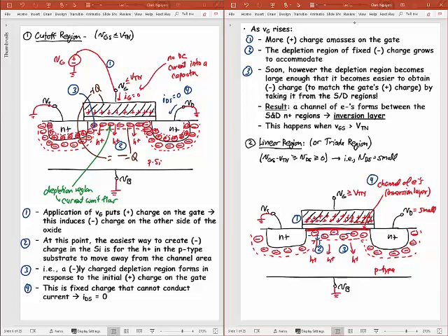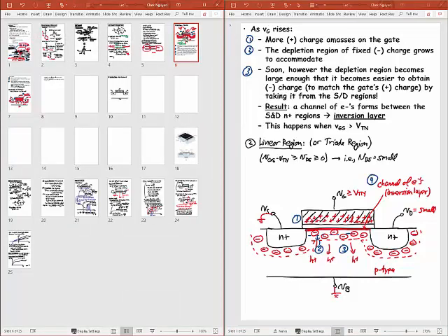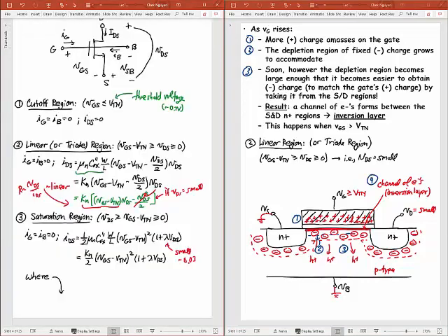Okay, so that's what's happening now for the linear region of this thing. So I'm keeping V sub d small. So I'm trying to stay in the linear region, which means I'm trying to stay in that region. I'll go back to this here. So I want to stay in this region. So I'm saying VDS is less than VGS minus VTN. So it's a small VDS. It's not this case yet where VDS is large, but it's this case where VDS is small. All right? And so with that, that's what I'm going to now analyze.